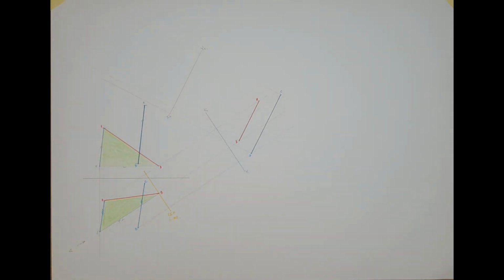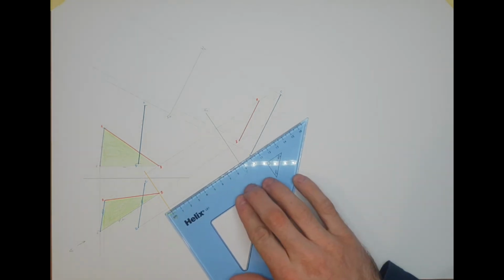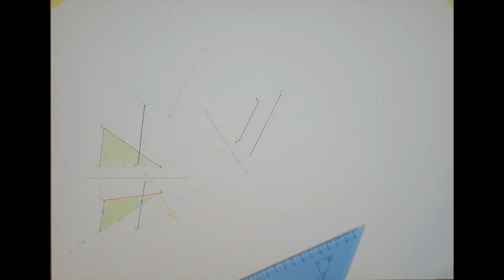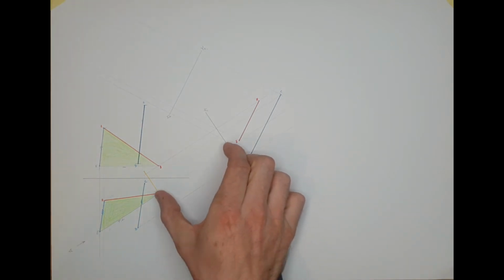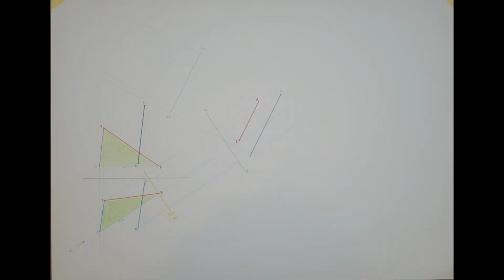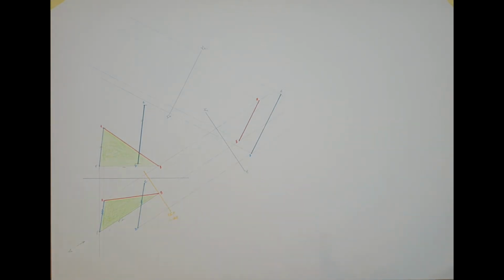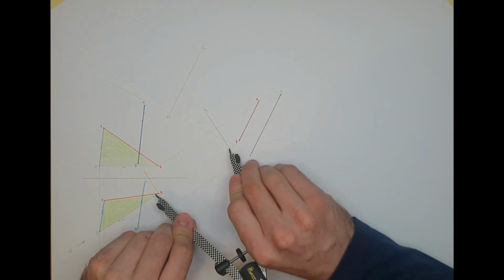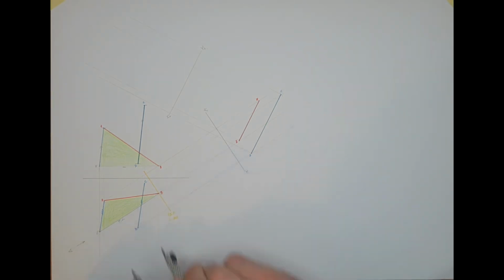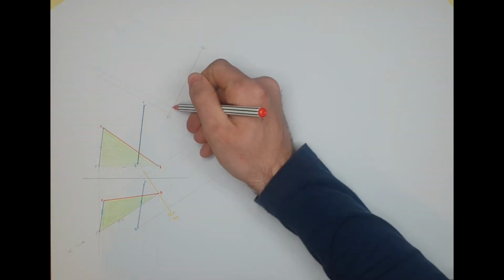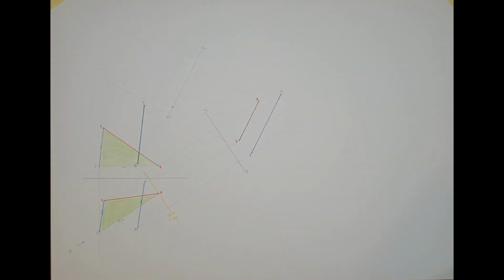But what that just means is that I have shaved about 87 or 88 mil off of every compass measurement. It just stops my drawing going way off my page, maybe even. First off, point B is now at a distance of 0, so instead of setting my compass to 87 mil to get point B, I'm just setting it to 0. So point B is right there at a setting of 0.